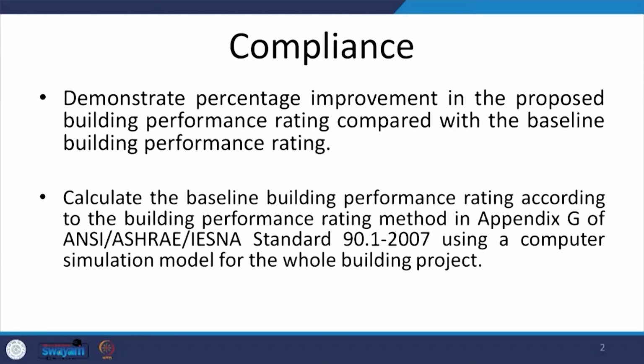When we are talking about compliance as per the whole building performance method, we have already seen that we have to demonstrate through simulation that either the energy consumption of the proposed case is less than that of the base case, as calculated through the EPI, energy performance index, which is a normalized rate of energy consumption, or that the number of unmet hours of thermal comfort of the proposed case is less than that of the base case.